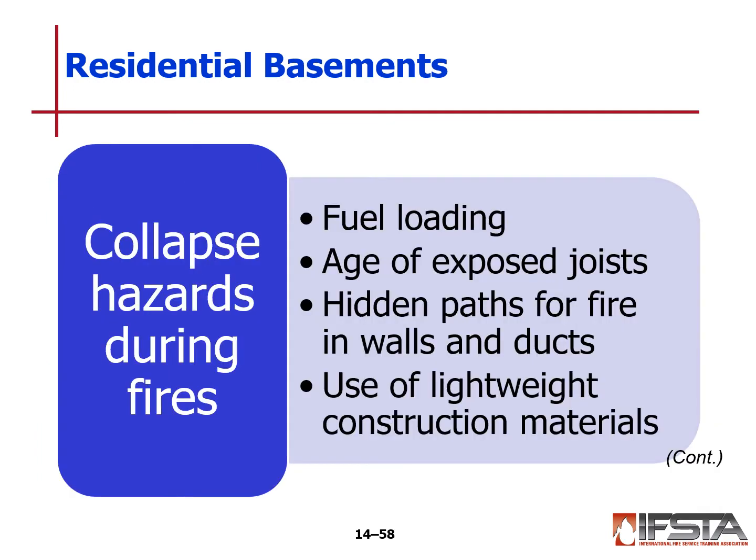The hazard of collapse during fires, a lot can cause this. Some of the things that have to do with it are fuel loading, the age of the exposed joist, and how it was constructed. Was beam technology like I-beam and lightweight truss construction type materials used, or was it just done with regular dimensional lumber type joists? And also the hidden paths for fire to travel in ducts and walls and that kind of thing.